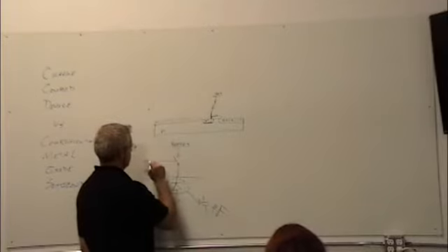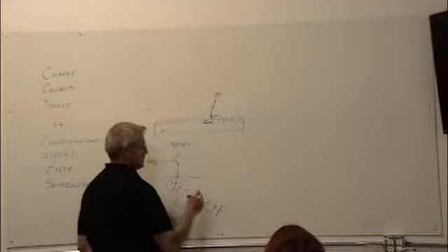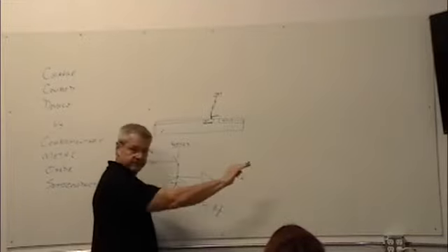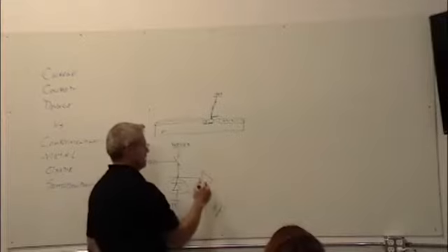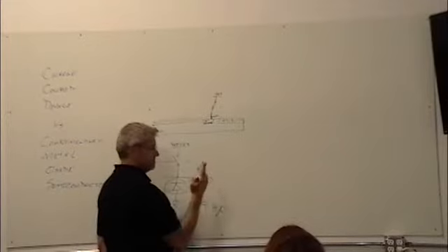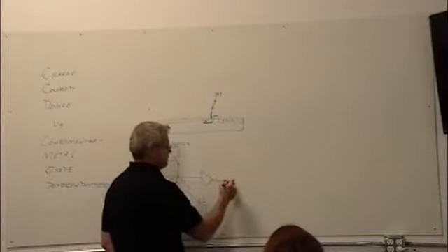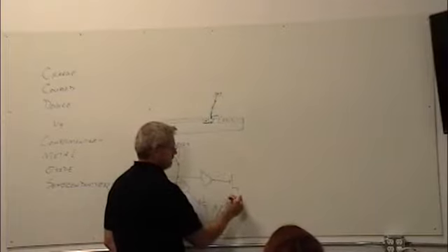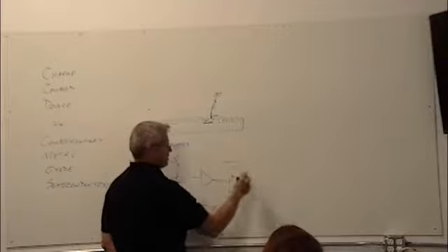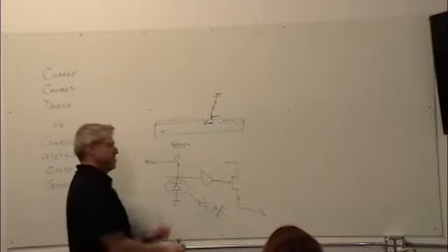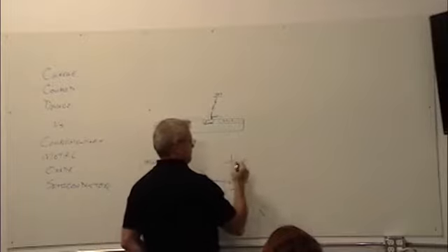So we send in a reset pulse. And then this drives an amplifier set. The way this amplifier usually works, it's usually only 2 or 3 transistors, and the output is usually an open emitter like that, so it's a current driver with some other voltage here, V out.